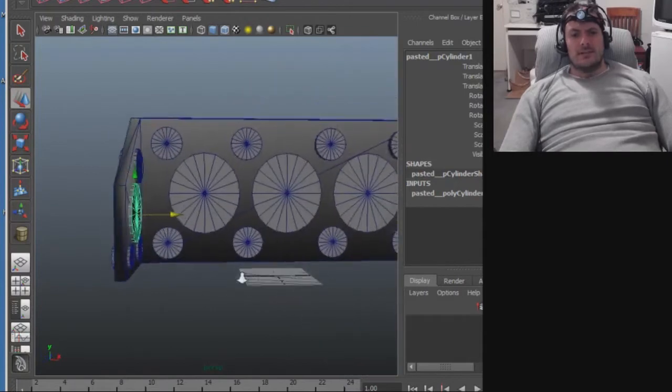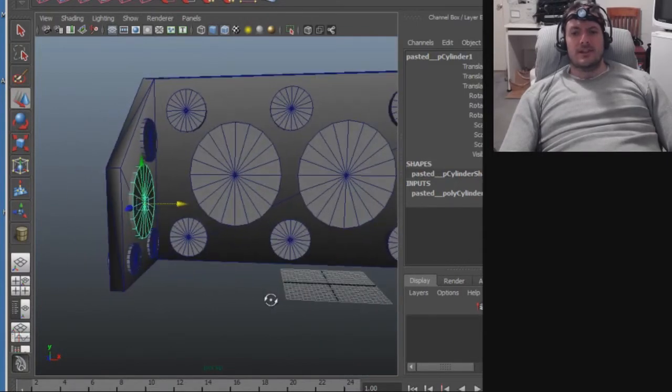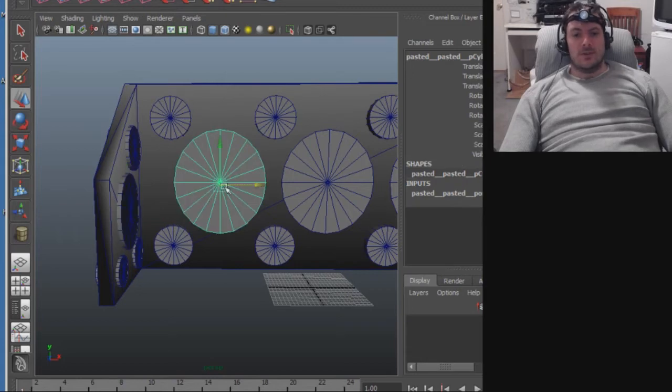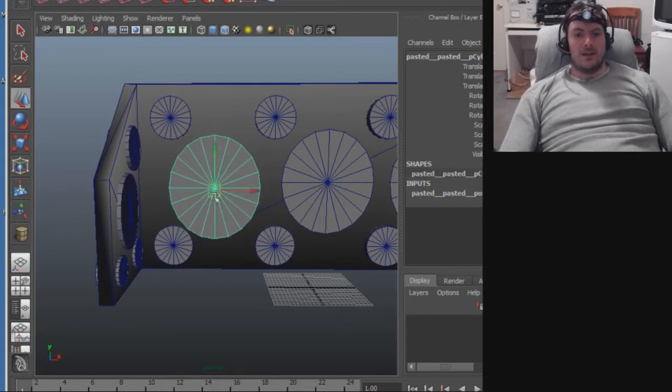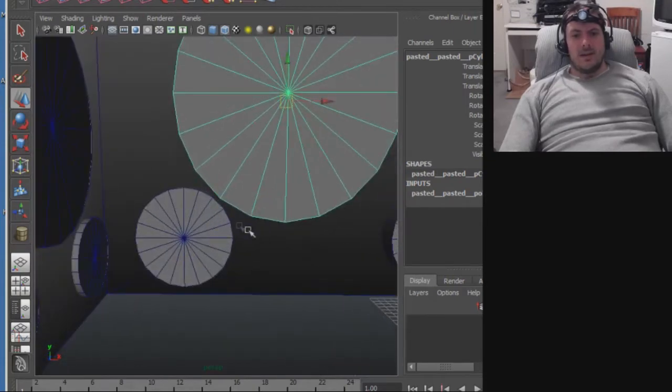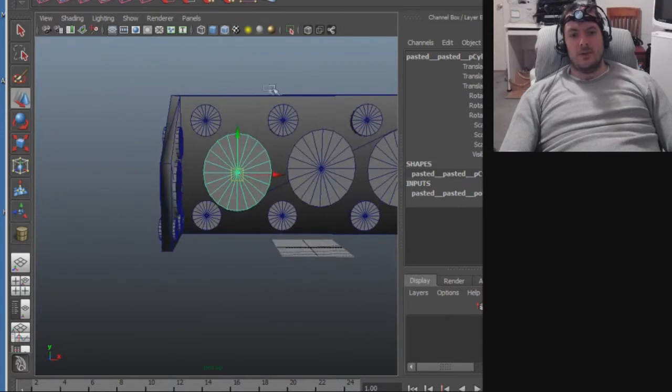Now you also have to take into account the architectural strength. So if you remove in your mind all these circles and just leave what's remaining, it has to be architecturally strong. So for example, you can't put this circle right here because then this will be a weakness. That can break too easily. If you were to stand with your foot on top of this top ledge, you don't want that force to transfer through here, and through here, and snap this right here at the weakest point.